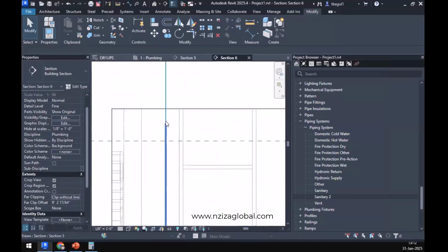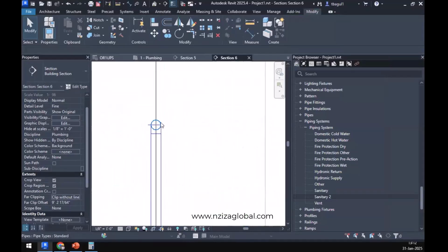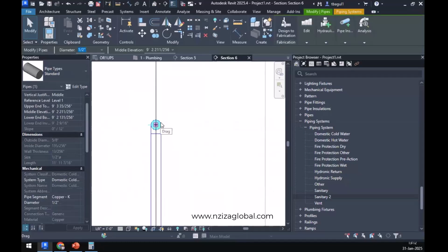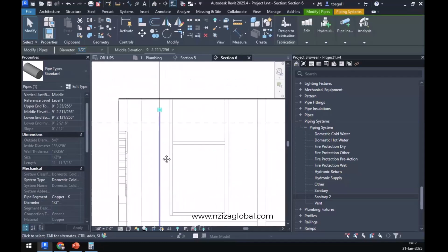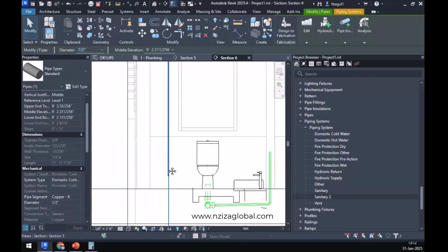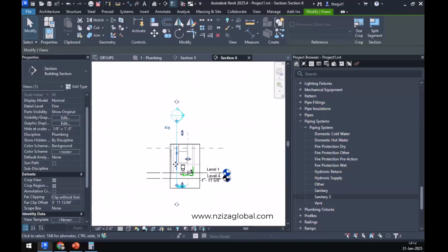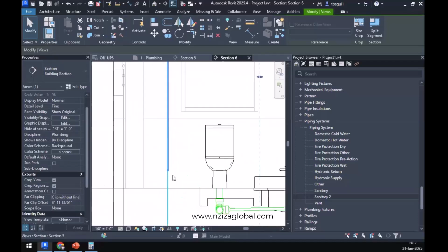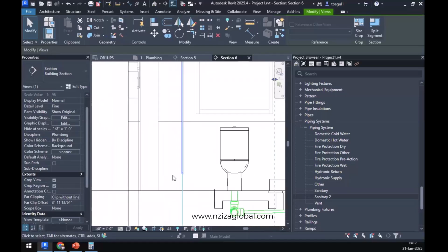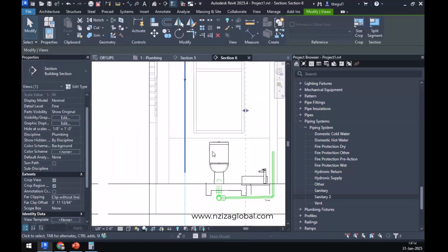All right, over here this is the pipe that we had coming up, right? It's supplied to the water closet. Again, this pipe got drawn at the exact center position where I had the section and we were looking at it from the section view, right? So let's make sure that we have it properly coordinated, because we do have a window, so we cannot drop the pipe directly through the window.